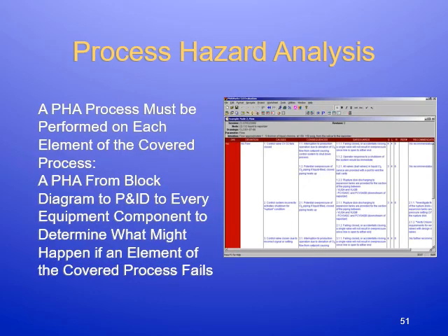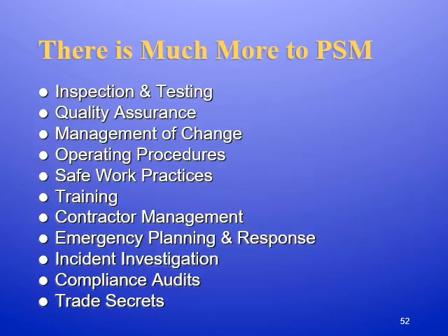A process hazard analysis must be performed on each element of the covered process. In a PHA, you have to look at block diagrams and every equipment component to see what would happen if that element in that process might fail.